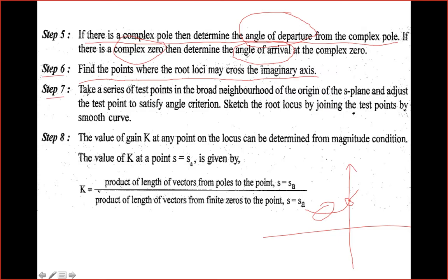Take a series of test points in the broad neighborhood of the origin of the S-plane and adjust the test point to satisfy the angle criterion. Sketch the root locus by joining the test points by smooth curves.